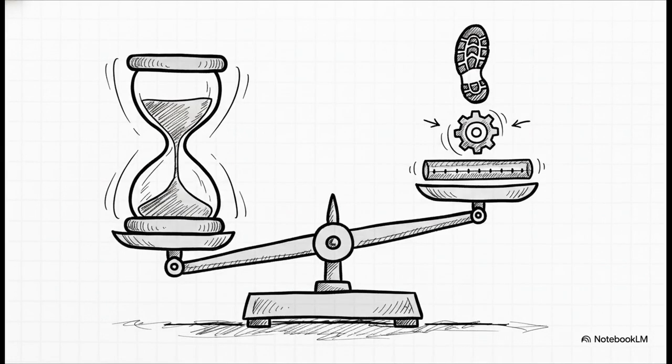And of course, every single pass takes time. Machining time, or TM, is dictated by a really strict mathematical relationship. It basically links the total length of the cut to how fast the tool is moving, which, as we know now, is our feed rate. So a longer part, a slower spindle speed, or a smaller feed stride are all going to increase your total machining time. It's this giant, delicate balancing act to optimize efficiency.